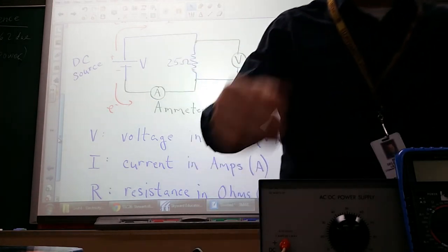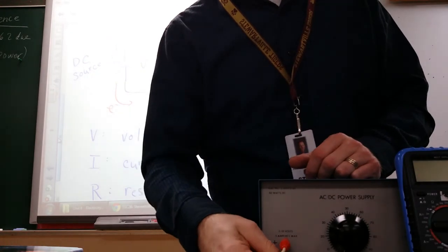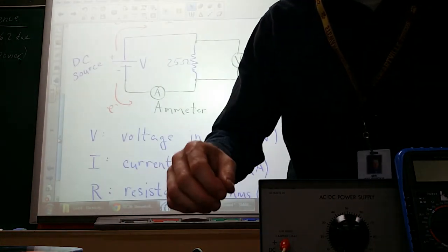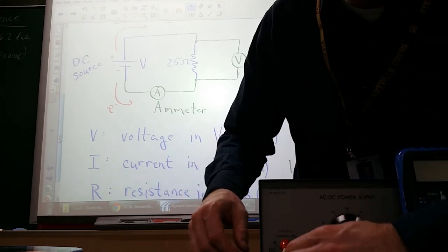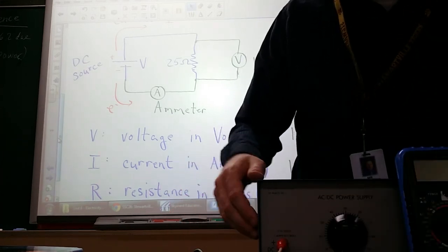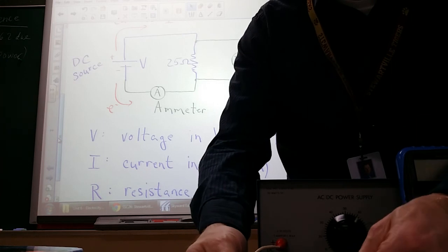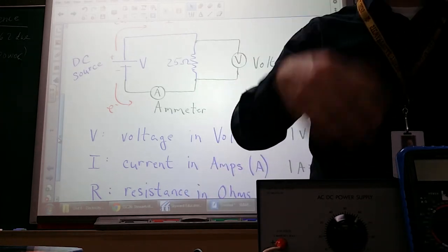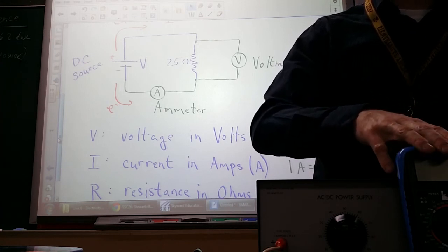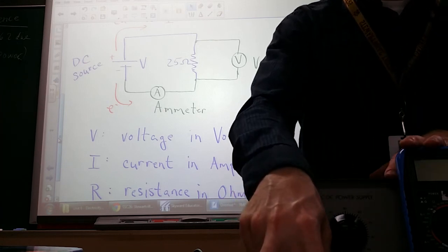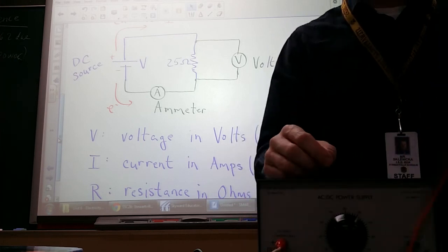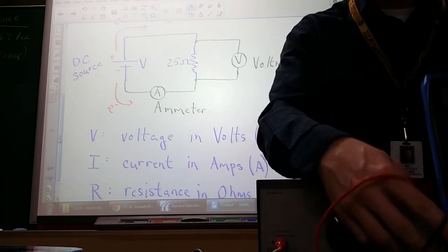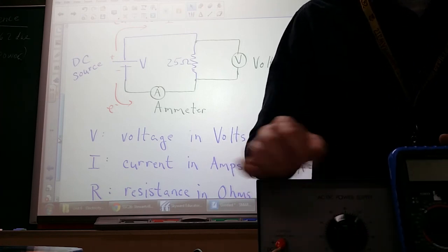So the electrons flow through it as though it were a wire and get counted. So I'm going to disconnect one of my alligator clips and put these two in their place. So one to the supply, the other to the other side of my resistor, and then as this goes up, it'll just report the current here. So if I have two, I could just leave them clipped on the two sides of the resistor and going from the power supply to the resistor, either side doesn't matter, and do that.